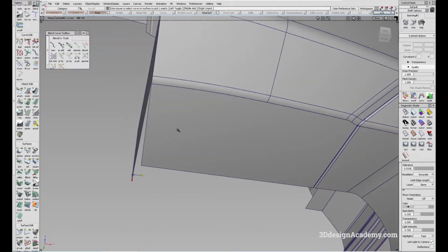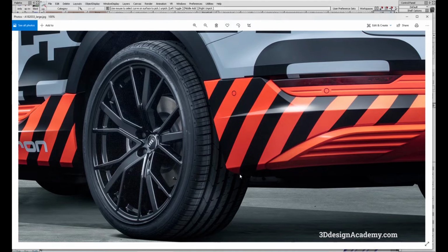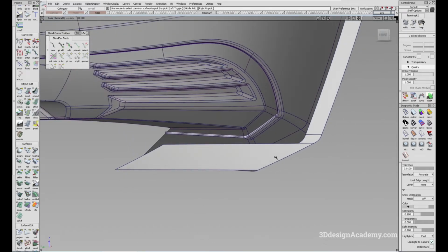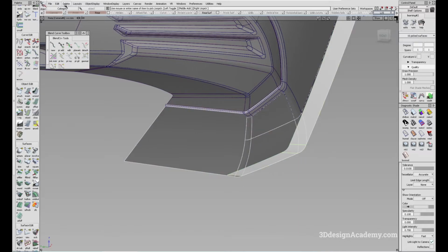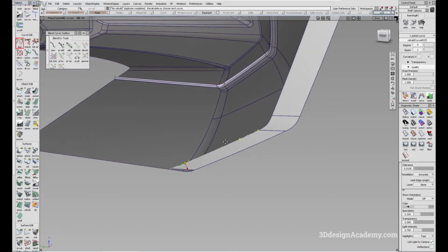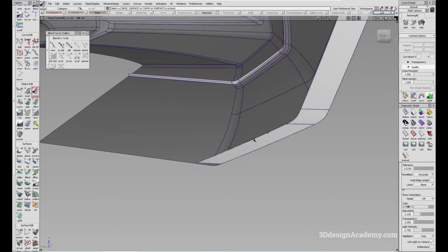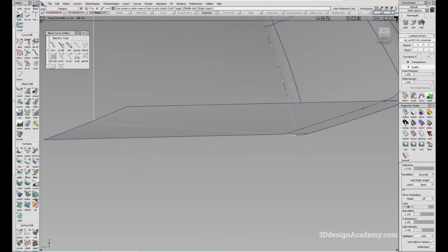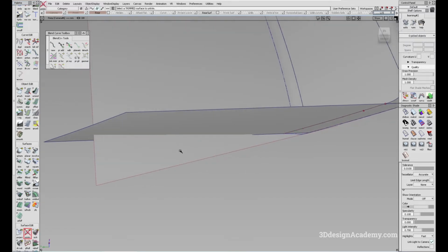Now, I don't know if it actually looks like this in production environment. I know this doesn't seem short, but it doesn't seem excessively long either. So just based on visuals, I think I'm just going to leave it like this. That said, however, I want to make sure to trim this piece over here. So before I extend it, let me just go back using Control Z, and let me just duplicate this piece over here. So I just duplicated the curve, and I'm just going to extend this one over here like that. And I'm going to also untrim this piece like that so that I can intersect these pieces.